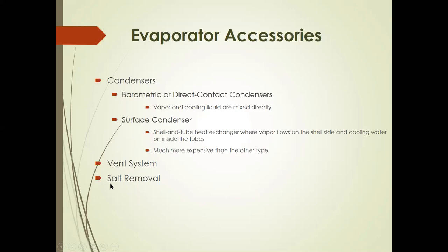For the salt removal system, this is for the case of unavoidable formation of salts or incorporation of salt in your solution to be concentrated inside the unit. So there has to be a settling zone for these solids, these salts, to be later on collected and removed from your unit.